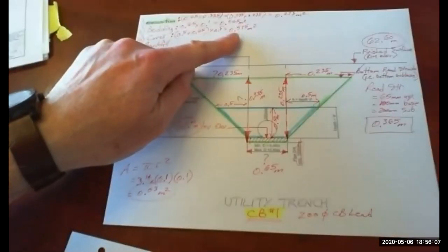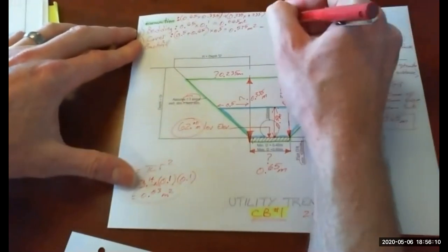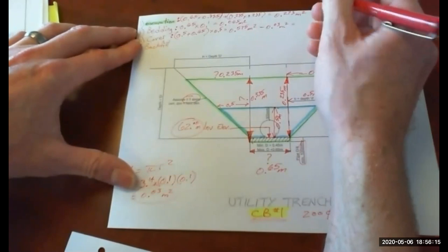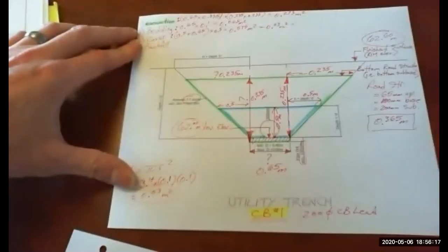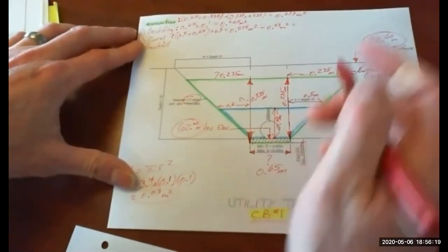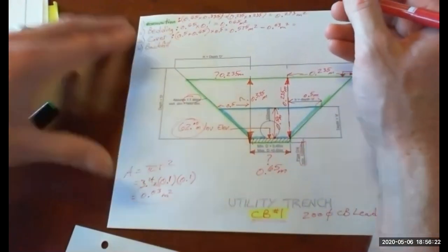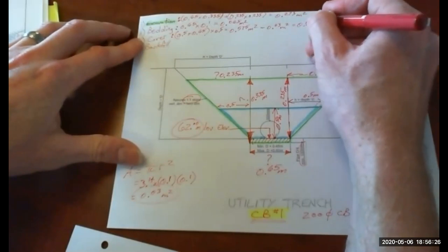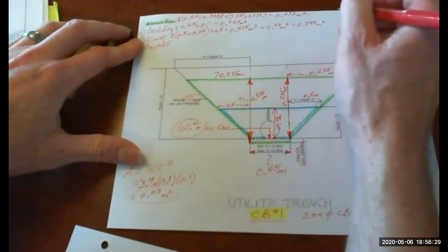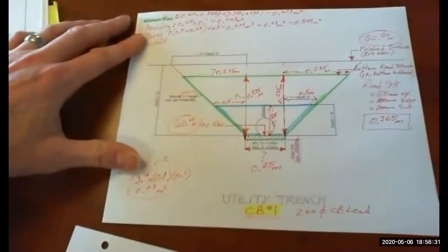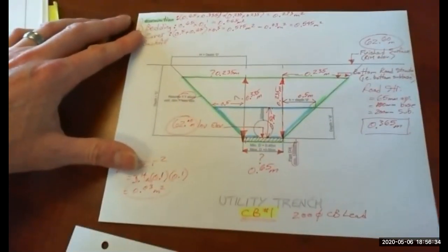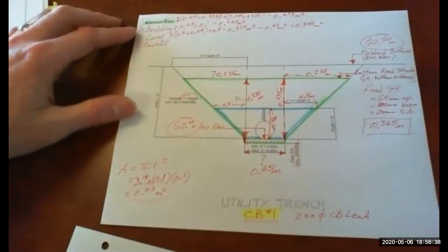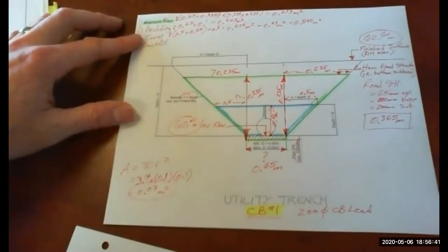from our cover area. So if we subtract 0.03 square meters, so 0.575 minus 0.03, that leaves us with the overall cover amount of 0.545 square meters. Notice these are all square meter calculations. So we're calculating areas here. We calculate volumes next. So what's the backfill?